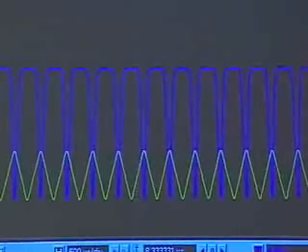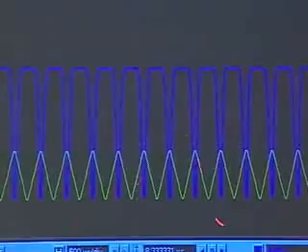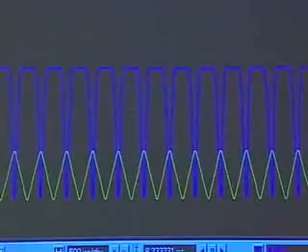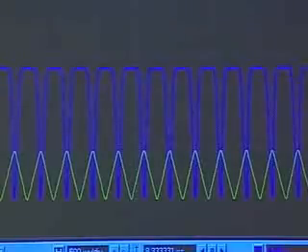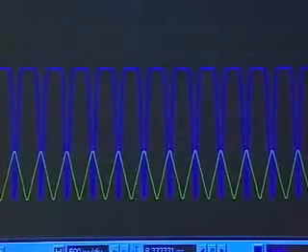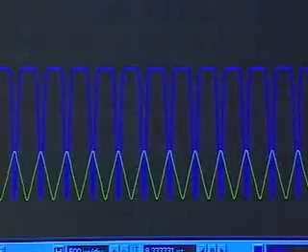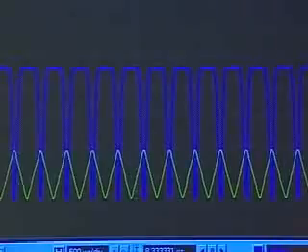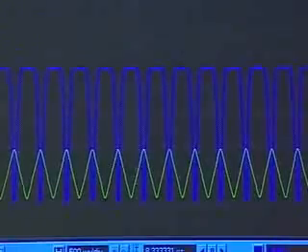Okay. So the triangular wave is my input, and this is my output. This looks nothing like a triangular wave, and the reason is that I don't have the right offset. So what I'll do is gradually increase the offset on the MOSFET. At this point, the offset is very low, a very small, near zero offset, and therefore my output's a disaster. My MOSFET is not in saturation all the time. So what I'll do here is apply some suitable offset.